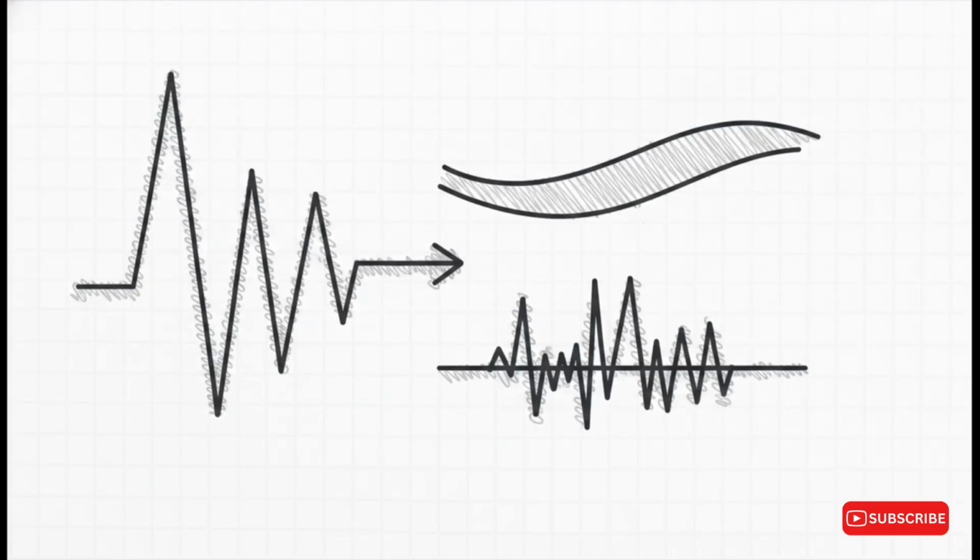So to make these calculations feasible, we use something called Reynolds decomposition. This trick separates the chaotic, instantaneous flow into stable, predictable averages alongside the high-frequency fluctuations. Essentially, every fluid property gets split into a nice, smooth mean value and a chaotic prime value that's just jumping wildly up and down over time.